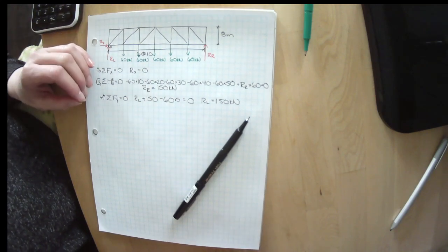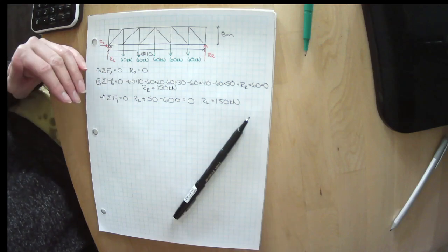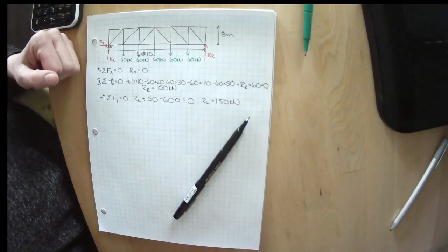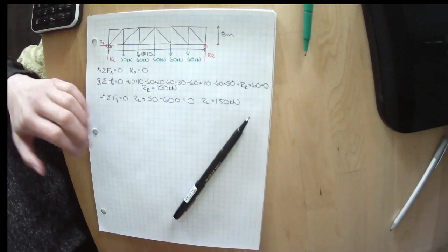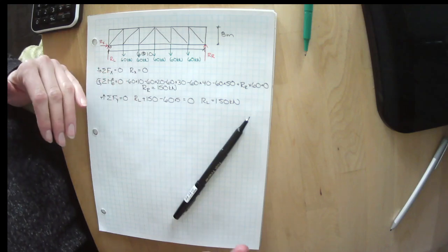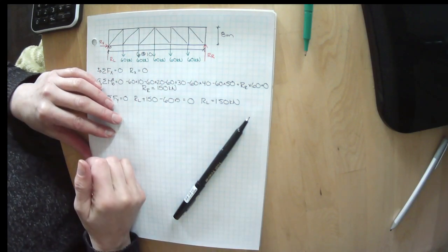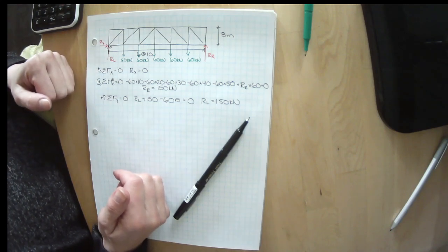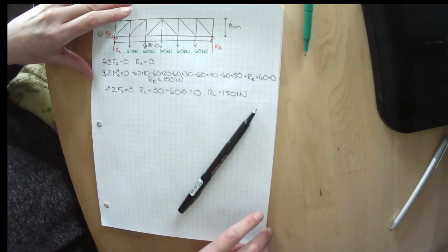So in your project, you are going to have a truss that is a roof truss, and those typically get loaded at the top. So similar to our last example, the point loads would come in to the top chord of the element. This example is more like, I don't know, a train bridge, a trestle bridge, where the loads would be applied to the bottom. So don't just assume because I've done an example where there are loads at the bottom that that is where the loads are in your project. Your project is going to have the loads coming in at the top.